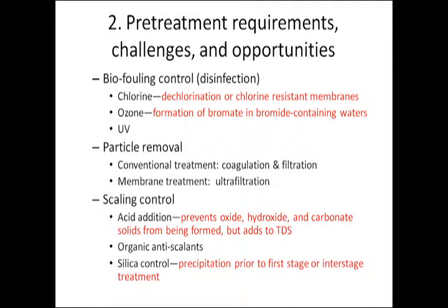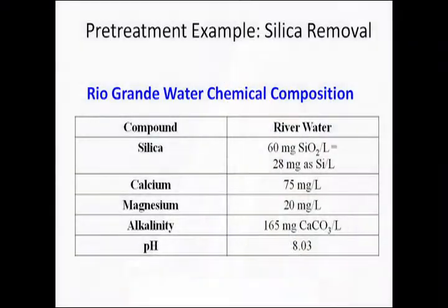output from desalination membranes. And I actually had a PhD student a few years ago who did some work on that. I'm going to just show you a few of the slides just to give you an indication of the kinds of things that are done. This water that we were using was from the Rio Grande. Near and dear to Ed's heart. This was actually from much farther southwest along the river, but in any case, this is a composition of the Rio Grande water, and it has a very high silica concentration in here. Also has calcium, magnesium, alkalinity that are important to be concerned about.